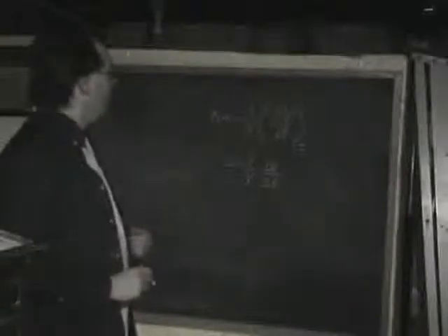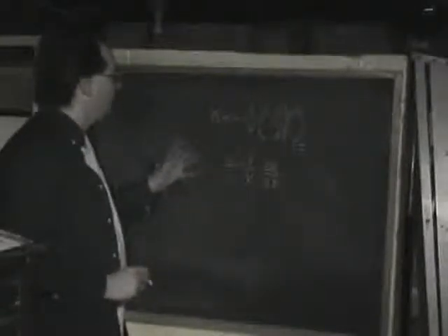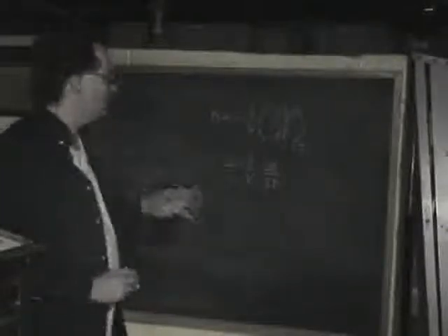So we'll just assume linearity throughout the region we're working with, which is probably a pretty good assumption. Throw away the differential calculus and replace our differentials with deltas. So this just becomes 1 over V times delta V, the change in volume, over delta P, the change in the pressure. Now, we do need to get this from volume to density, because we were working with density, and this is in terms of volume, but the relationship between them is simple.